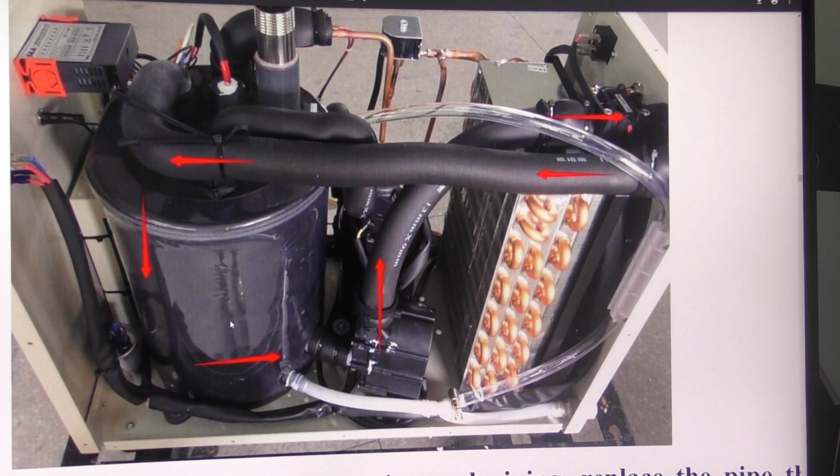In less than a minute we're going to get a rapid cooling into these pipes that are running out to the tube. I mean, it's not doing any damage to the tube, but it might be affecting your cutting performance. It certainly affects your dithered engraving performance, as you can see. So I think it falls upon you to deal with this problem with an intermediate buffering tank.